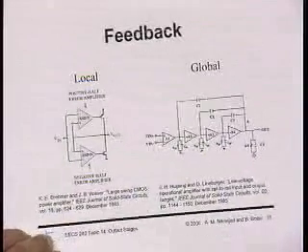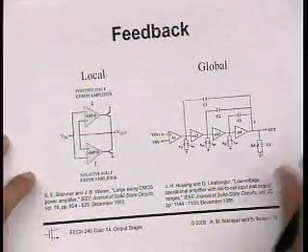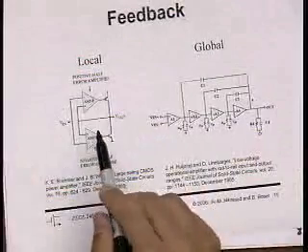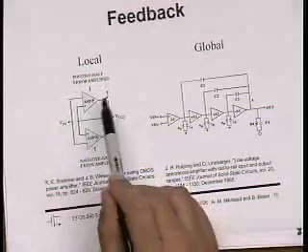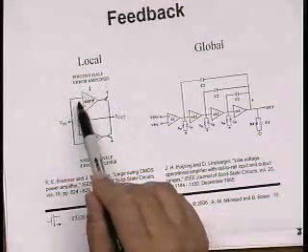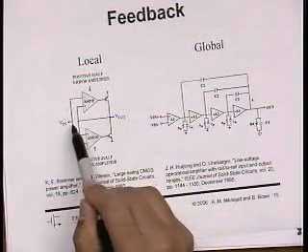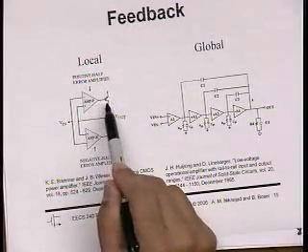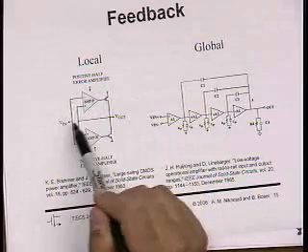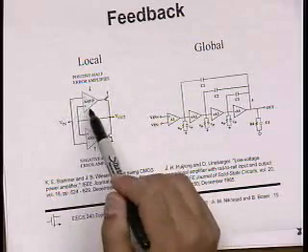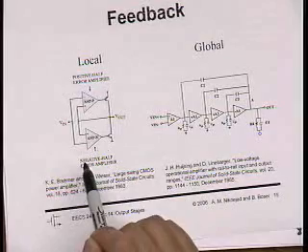There's a couple of other ways of doing output stages that we're going to look at briefly. Instead of using shunt feedback, as we did, we can also use amplifiers in our loop here. And we'll talk about this. This is an error amplifier. It basically takes the output voltage, compares it to the input, and produces an error signal. And so this amplifier is extremely linear. So if you have applications where you really need a linear output stage, this is a very good solution. We'll talk about some of the issues, though, with this.